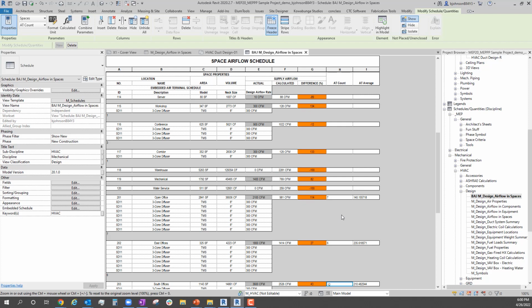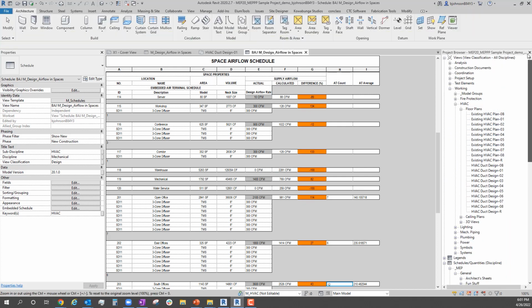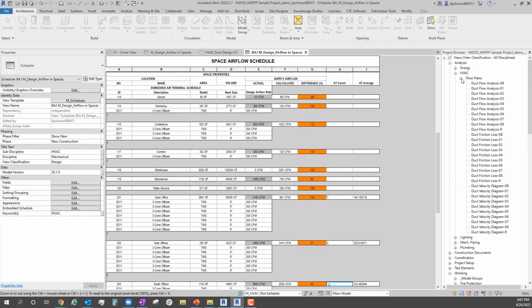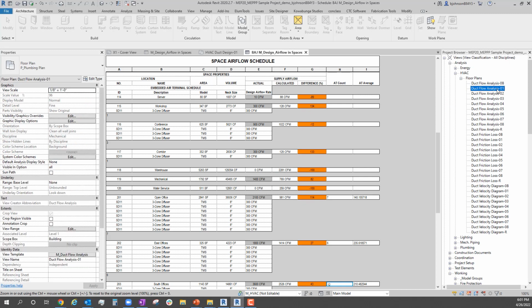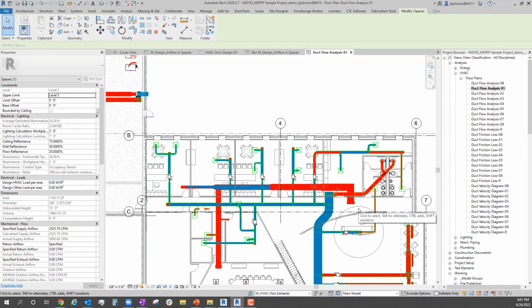If I've done all that, then I can run my sizing routines and have it auto-size down or up to the actual size based on the connector in the true CFM. Right? So I'm actually using Revit tools to go back and resize all of my elements. And then inside the productivity pack, we do have a little area up here called analysis, where I can look at 3 things. CFM, and my demo is a little bit busted here, where I have a bunch of red stuff in here. Red is 0 CFM up to 5 CFM, and blue is everything that's normal, above 5 CFM.